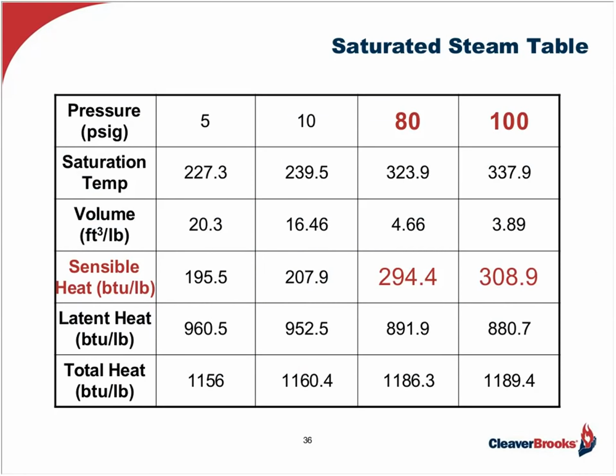Now, before moving on to the selection of the major components for the deaerator, I think I would be remiss if I didn't come back to capturing all the condensate we possibly can, as this is truly liquid gold. On the screen now, I've returned to the steam table just to re-emphasize again how much sensible energy goes into each pound of water as we increase pressure before arriving at saturation temperature. And at this point, you may be asking, Steve, well, why are you showing me steam tables highlighting 80 and 100 pounds when I've been talking about deaerators operating between 5 and 10?